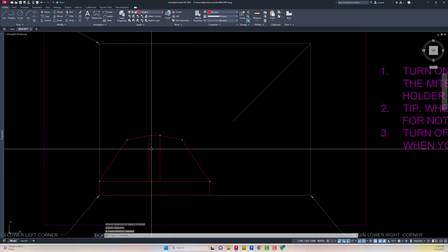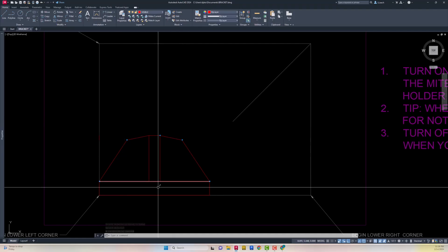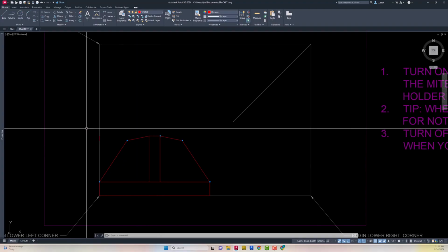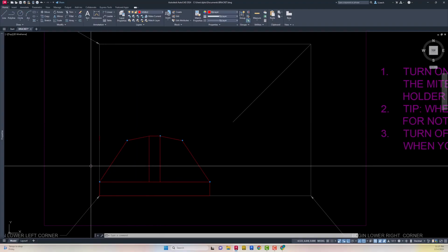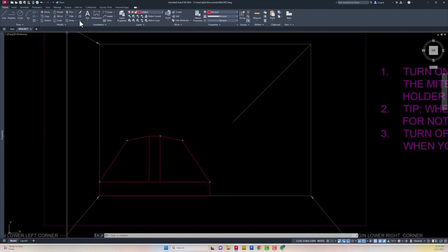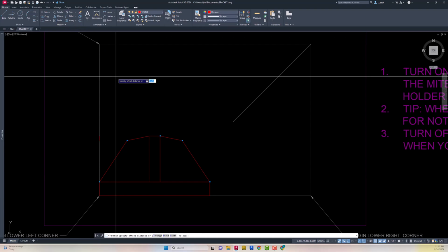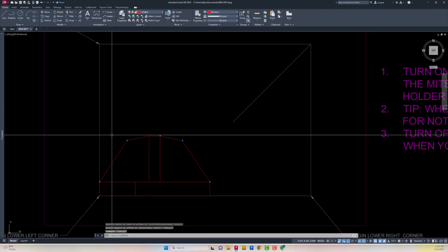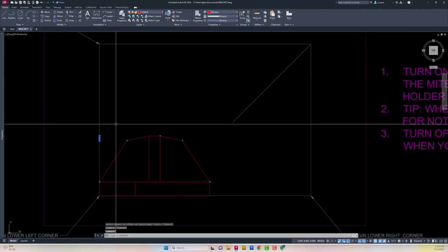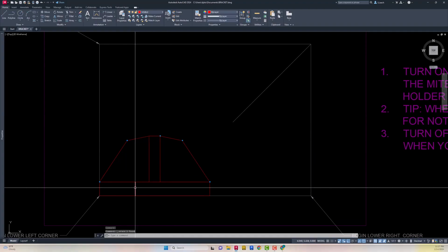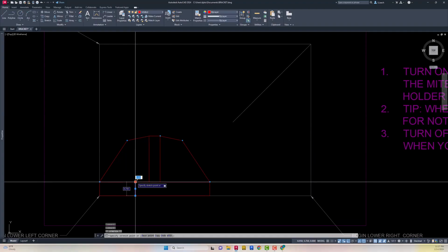Now we need to put our circles in. There are some slots that are going to be hidden lines. Let me think about this. Oh, so this circle is offset from this edge over to the right by 1.95. So I'm going to offset 1.95. I'm just trying to find the center of the circle. So from here over, I also have a line here I want to get rid of. Delete that. And I can click this line, grab this grip, and just drag it straight up.